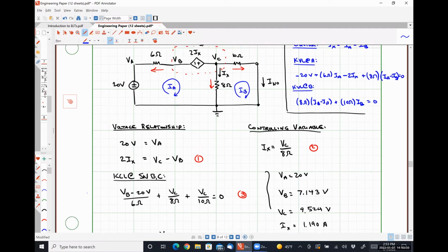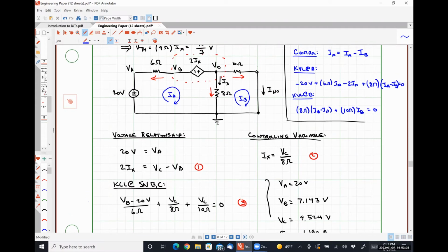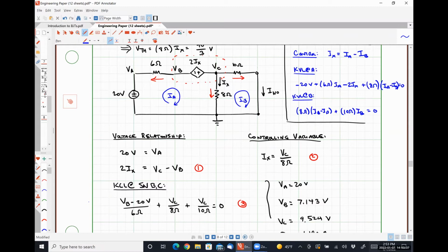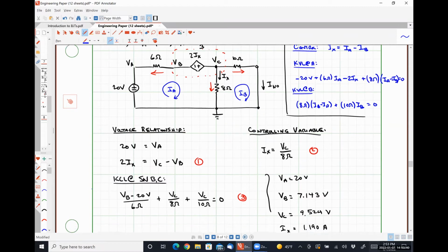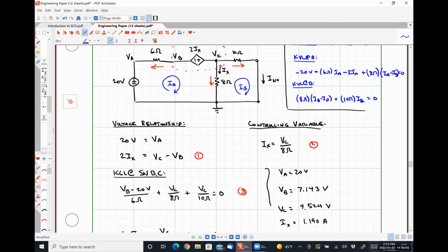and you should find, so it's 3 equations, 3 unknowns, including the quantity IX. You should find obviously that our IXs are the same, and you would find that I Norton would be the mesh current IB in this case. So if you want to take a minute or two to do that to verify it, by all means go ahead. Either way is an equally valid method of determining the Norton current for this circuit.